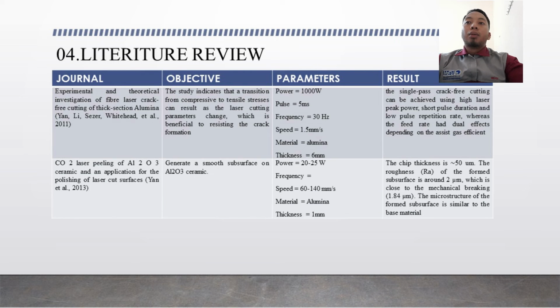The fourth journal for my literature review is "Experimental and Theoretical Investigation of Fiber Laser Crack-Free Cutting of Thick Section Alumina" by Yan Li, 2011. The objective is to study and indicate that a transition from compressive to tensile stress can result as the laser cutting parameters change, which is beneficial to resisting the crack formation.